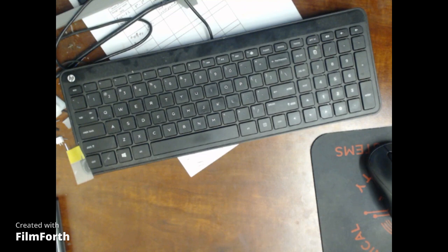Now, there are limited shortcuts on the keyboard, and sometimes you have to look into the software and hover over the icons. For example, hover over the icon for the line, and it will indicate the letter L. Another one is P, I hope SolidWorks has that one, it'll be pan. O will be orbit. Control Z will be undo.